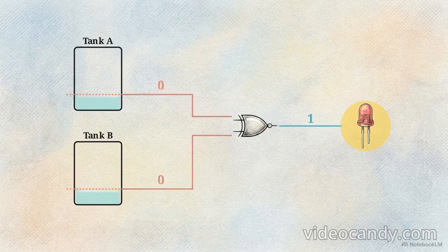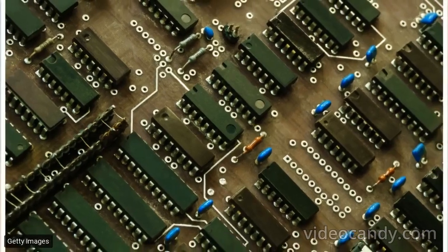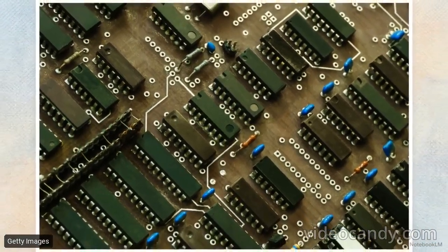safety indicator active. If both tanks suddenly drain below 25%, the inputs both drop to low. Because the inputs match, the gate still outputs a high, triggering an emergency response. Instead of wiring multiple AND NOT gates to evaluate this condition, the EX-NOR provides a highly efficient single-chip hardware solution for real-world parity detection.